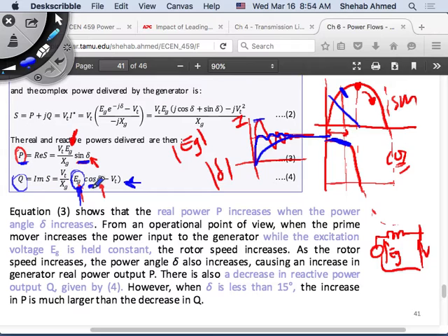and change reactive power, we know that for us to control reactive power, I will change E. If I change E, it's also changing the generator voltage, the real power, right? So I will have to also play with delta a little bit to be able to supply a fixed reactive power. But the changes will not be significant in delta to control reactive power.